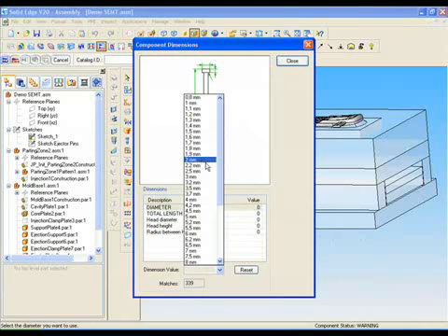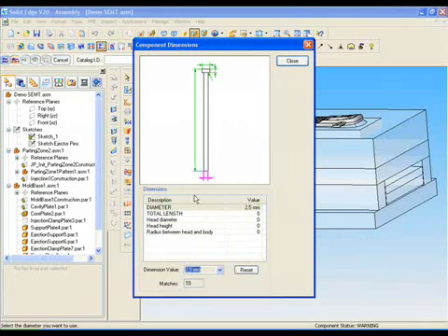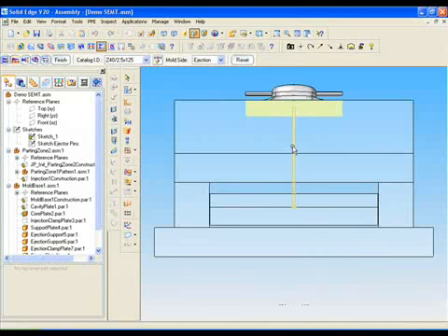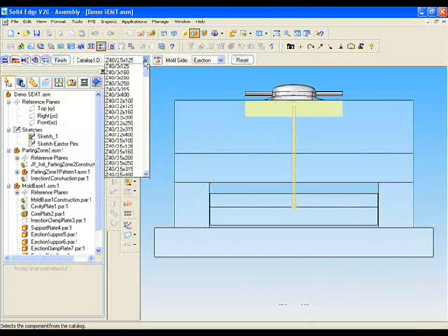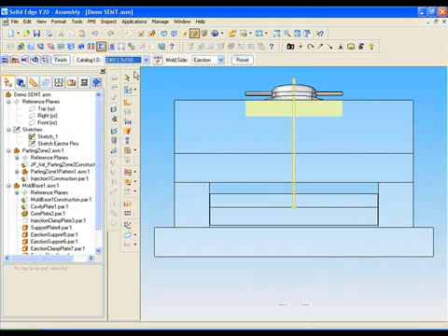The ones in capital letters are the main and the only ones that need to be set, as the others are dependent. Once defined, we close the Dimensions dialog and check that the ejector pin height is not enough to reach the part, so we will use the catalog reference to select the bigger height. We can immediately check that it now reaches the part, so we move to the placement step.